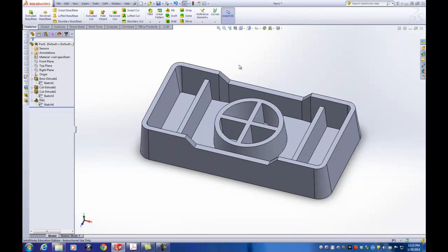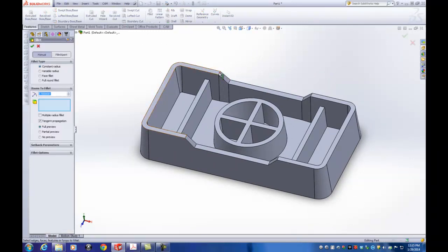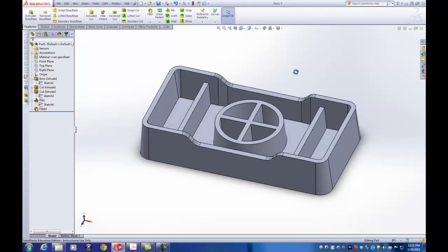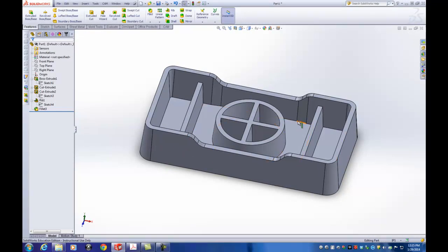And then lastly, you have some fillets to put in. So we'll do a fillet here and here on these 8 little corners at 0.5. Oops, don't want that one, so just right click, delete, and try it one more time. Okay, that's first. And then I want to put a fillet on everything else, but I don't want to sit there and pick one edge at a time.